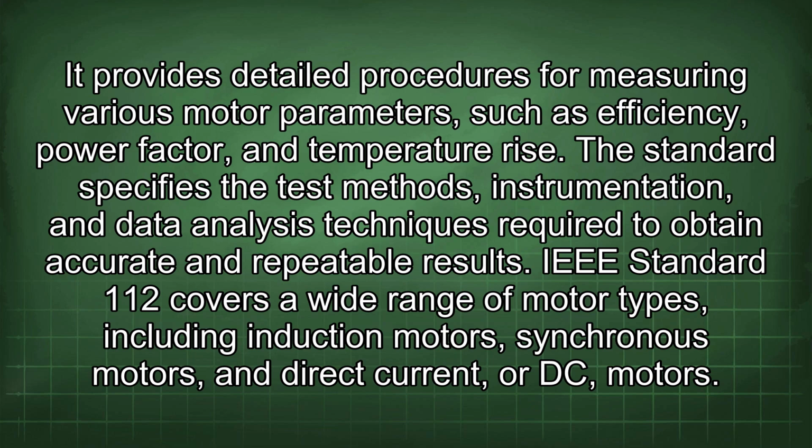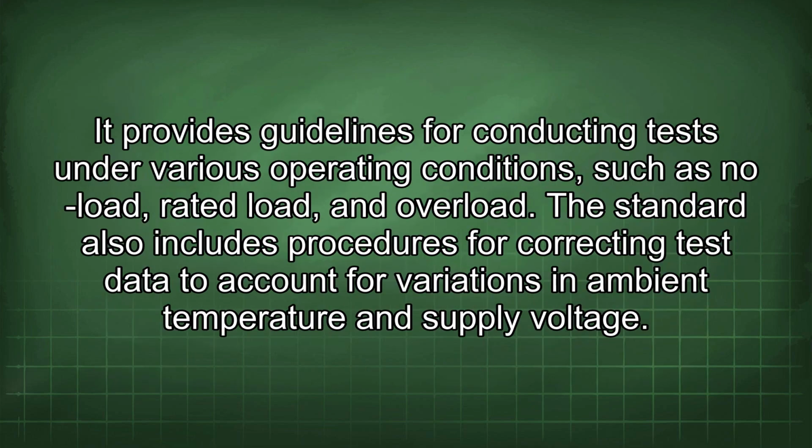IEEE Standard 112 covers a wide range of motor types, including induction motors, synchronous motors, and direct current, or DC, motors. It provides guidelines for conducting tests under various operating conditions such as no load, rated load, and overload. The standard also includes procedures for correcting test data to account for variations in ambient temperature and supply voltage.